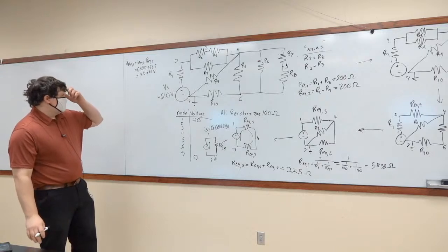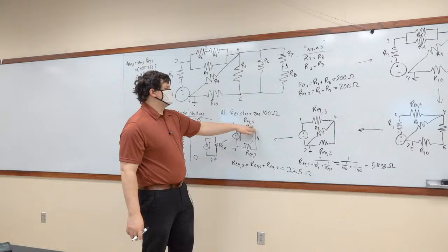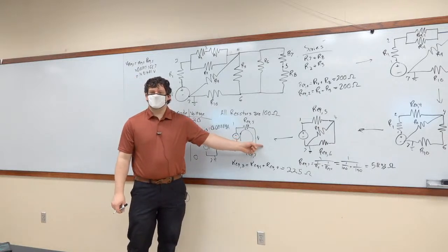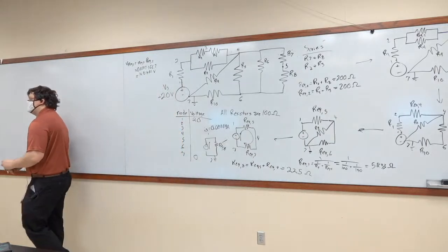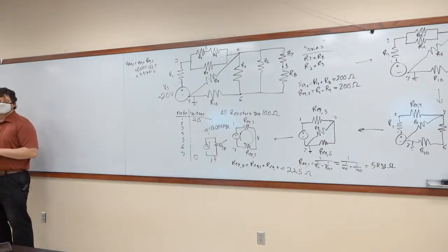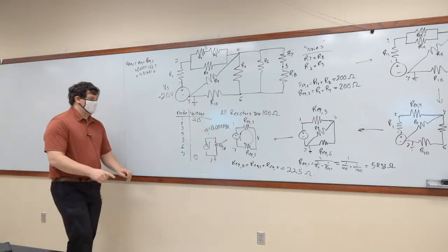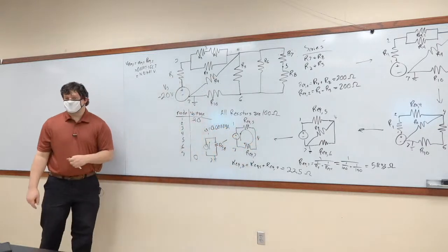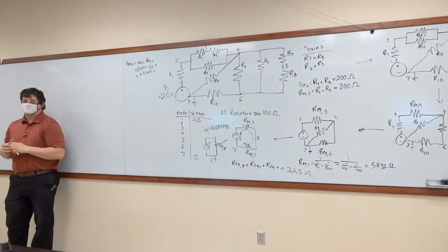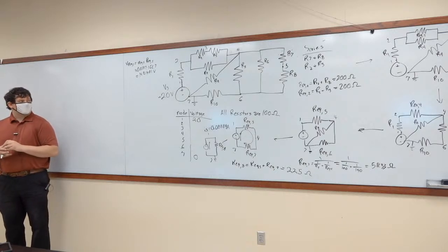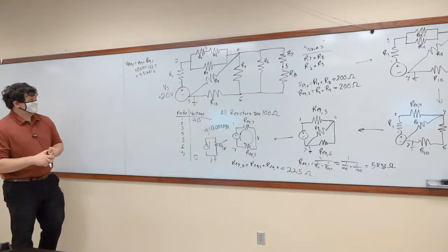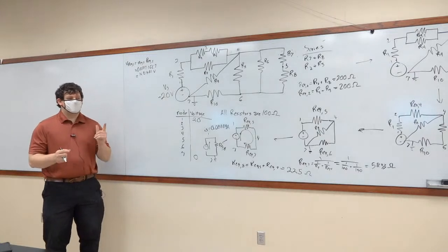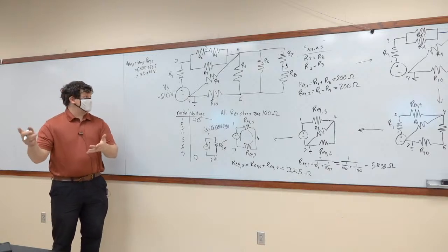Okay, now what we know is that the voltage across REQ5 is 14.814814 volts. Okay. Do we know what the voltage is at node 4? We can find it, right? We know the voltage at 1 is 20. Does it then decrease or increase by 14.81? Are we going to 34.814 volts? Are we going down to 5.185 repeating? Which one? Subtracting, right? We end up at 5.